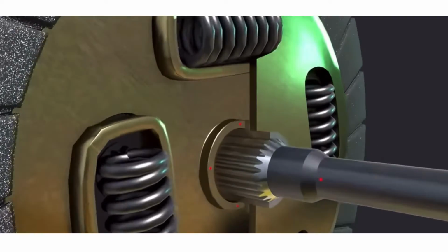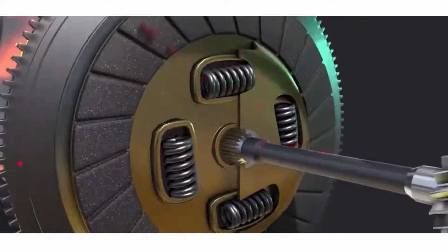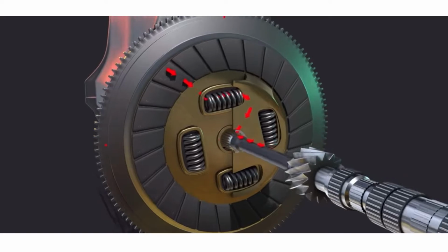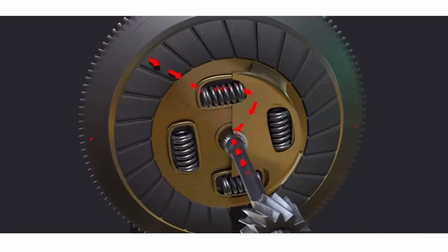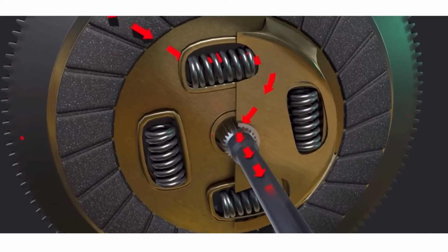The collar is splined to the output shaft, whereas the gears rotate with the lay shaft, and thus are on bearings on the output shaft. By locking the collar with a selected gear, engine torque passes from the lay shaft to the output shaft.